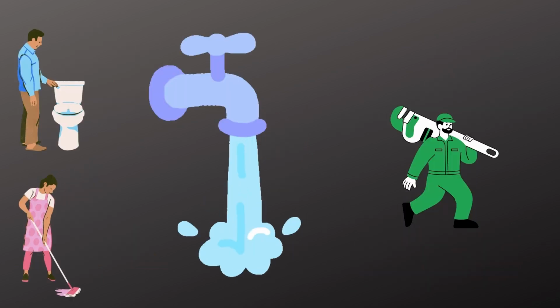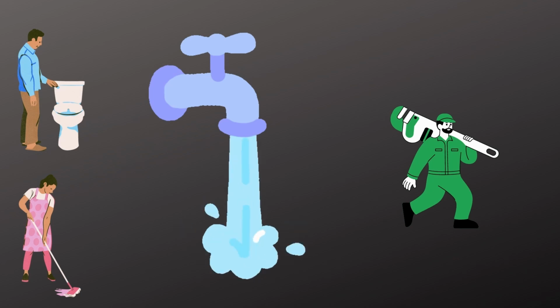Step number 10 is about the septic tank. Mostly countryside houses have septic systems. If there is no centralized sewage system available for the house, then you must have a septic system. Whenever we propose any drawings to the city and if we have a septic tank on a site, then we must show that septic tank on the site plan. We always require a minimum distance between the septic tank and a building for structural safety. You can find the distance in your building code.